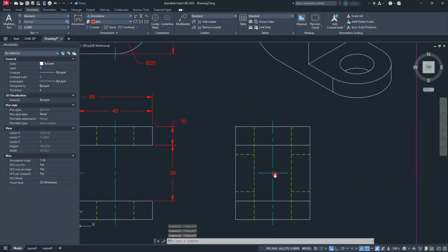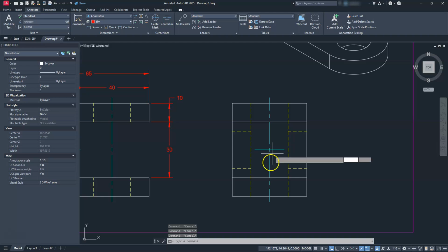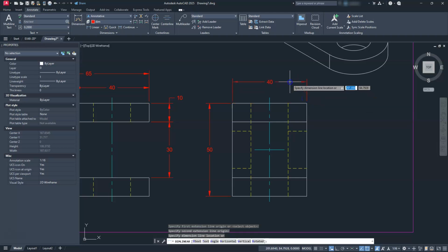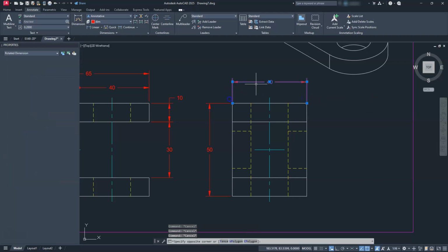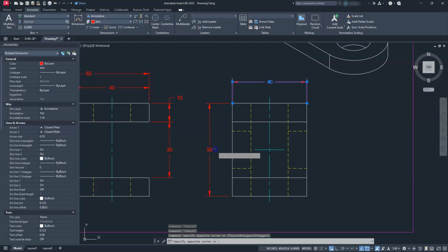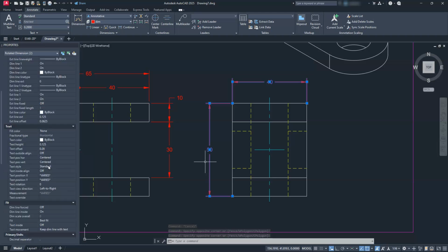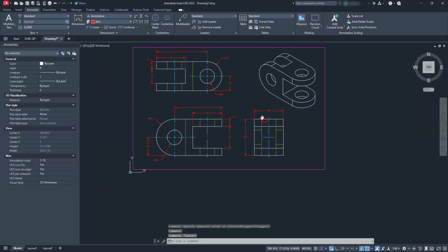Okay, lastly, what I need to do here is go ahead and put a couple of dimensions. So just a linear dimension from that endpoint to here, and also from this endpoint to here. Now we can select both of these, and that's exactly what I'm going to do. And then I will use my property window here. I will scroll till I see text. Then underneath the text overwrite, I'll start with the open parentheses, less than, greater than, close parentheses, hit enter. And like magic, both of those should automatically adjust.